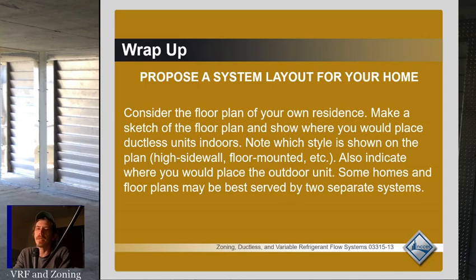Everybody sees these mini splits in relatively small spaces and they think, oh, this is the best thing in the world, right? You just have this one unit in the room and it does everything. But if you need to do that on a larger footprint, it's not going to be anywhere near as comfortable as a well-designed ducted system, right? Because you've got more places to move the air when you're running the duct. You've got more control over that. So that's one thing to note.